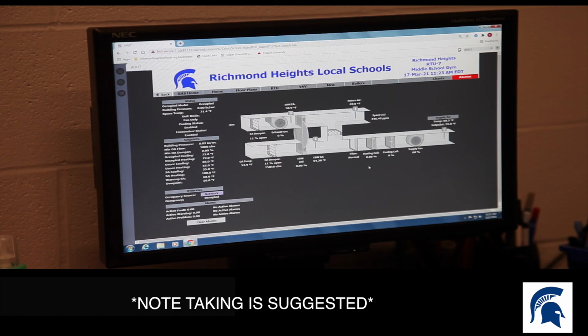And what usually that means, you have an issue either with your dampers aren't actually stroking how they're supposed to stroke, or your heating coil is having a problem where you either don't have hot water, which would then be affecting the whole building, or it might be the hot water valve, the actuator on that valve just isn't opening or closing like it's supposed to.